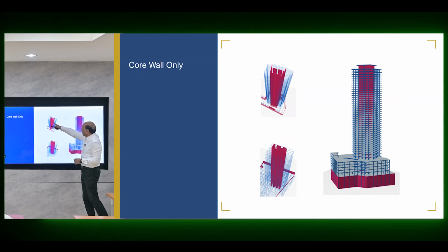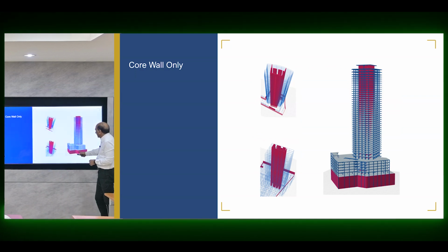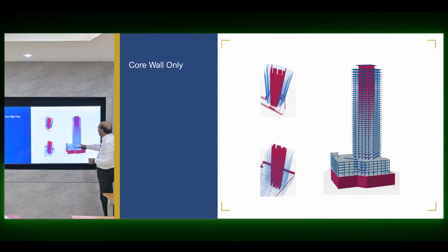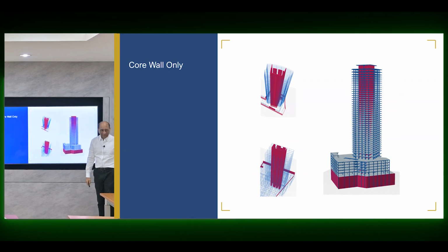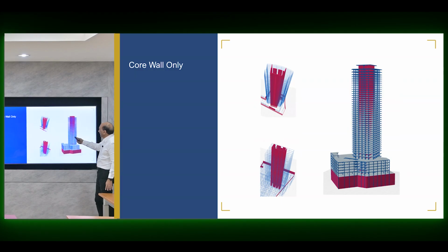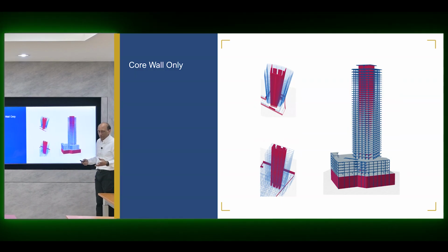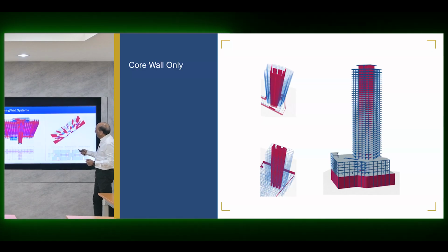So this is using a very large core wall system. There's a basement here, there's a podium here, there's a core wall, a very strong core wall. So flat slab will be fine here, for example, because it's not too high and the wall is really big. And it's a core wall, which is probably also coupled within the system. So it's not a problem.